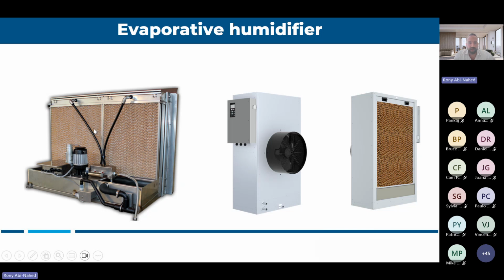So you have here the option to have a pump to recirculate the water. So you're kind of using the same water. When you go with this option, you normally have UV lighting to make sure that the water is clean of bacteria before running it again. Or you can have the option to go direct feed, which means all the water that goes here will just go to the drain. You don't recycle any of it.